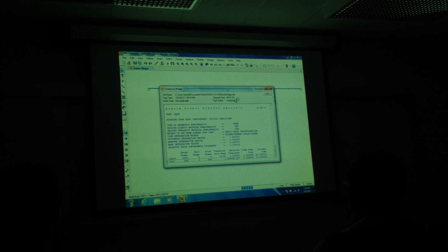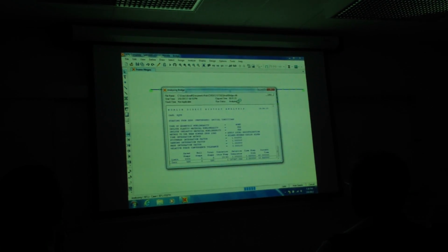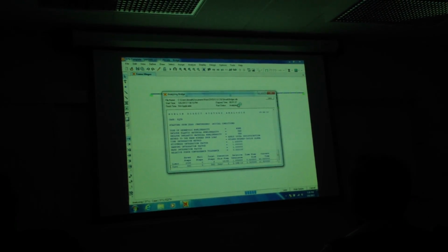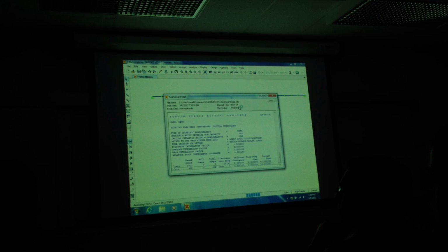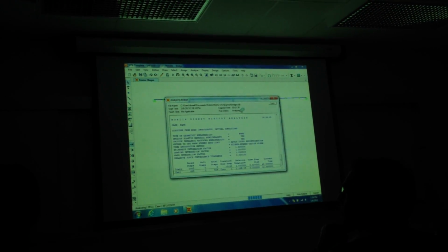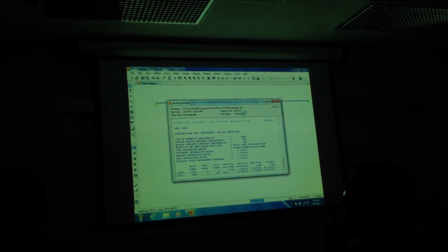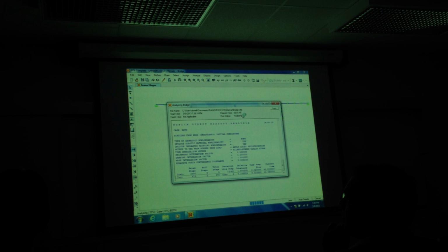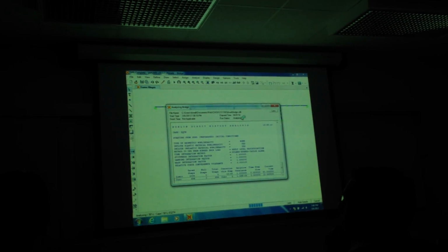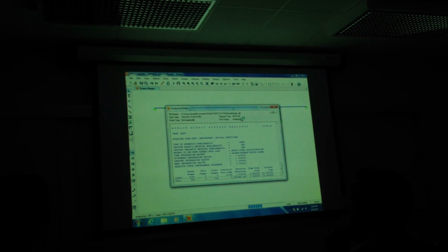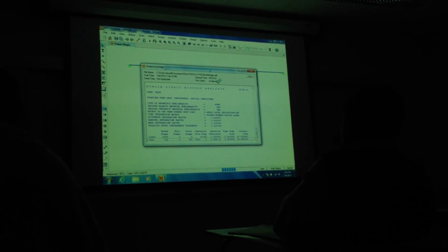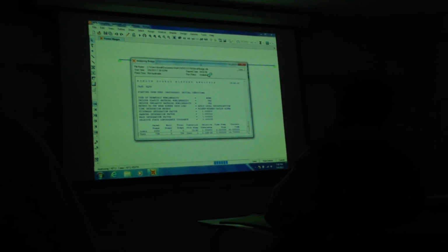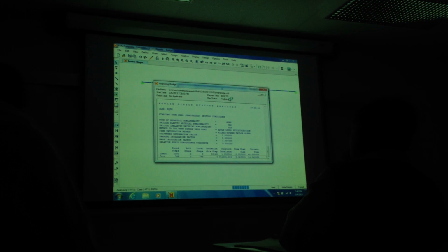We're at about 1/4 of the way, 10 seconds out of a 40-second earthquake record. So you can see, this is why the industry fights us. I'd like to see nonlinear analysis used in everyday design of bridges and building structures. But when you develop a complicated model, this is just a simple model we have for the bridge, it's not that detailed, right? As you get more detailed, it takes longer to run, and for production purposes, it ends up being difficult to use nonlinear analysis. Nonlinear analysis is good because it represents the physical behavior of the structure under an earthquake. They're always designed to go nonlinear, but they're not analyzed as nonlinear. Simplifications, like the divide by 6.